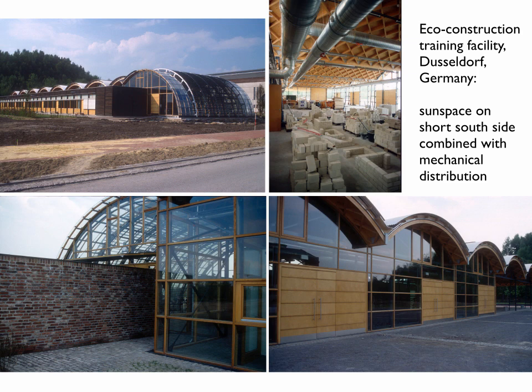It's got east-facing glass, it's got west-facing glass, it's got glass that faces straight up. It's also got a series of louvers on top that allow that sun to be controlled in the summertime, and that sun space can be vented out. But the key thing here is that it's collecting on the south end of the building, and then it's integrated into the mechanical system. So for all that glass, you can't even put enough mass in that building, even though it's got a mass floor and a mass wall. It's got a ton of glass.